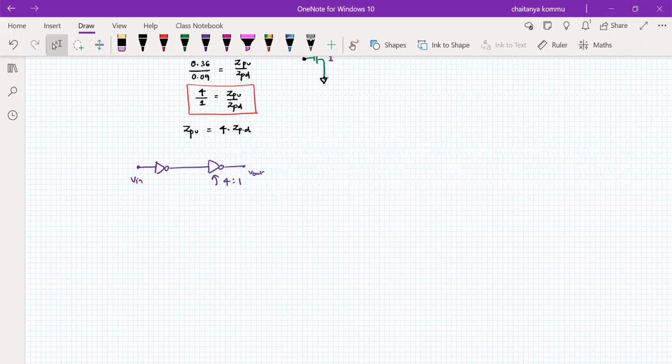resistive pull-up. The second one is depletion pull-up, because the depletion pull-up is better compared to the resistive pull-up. But the depletion mode type of transistor also consumes a lot of power. Therefore, what is the problem? We cannot use this depletion mode type of transistor if the power requirement is very stringent. That means for low power consumption devices, this device is also not applicable.